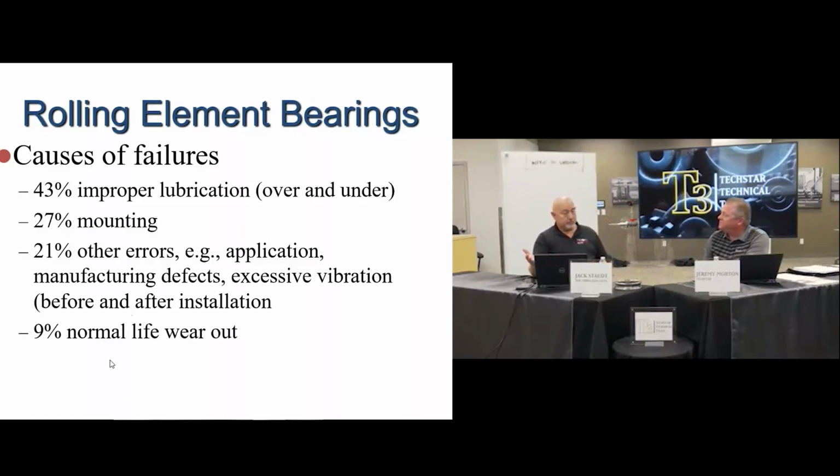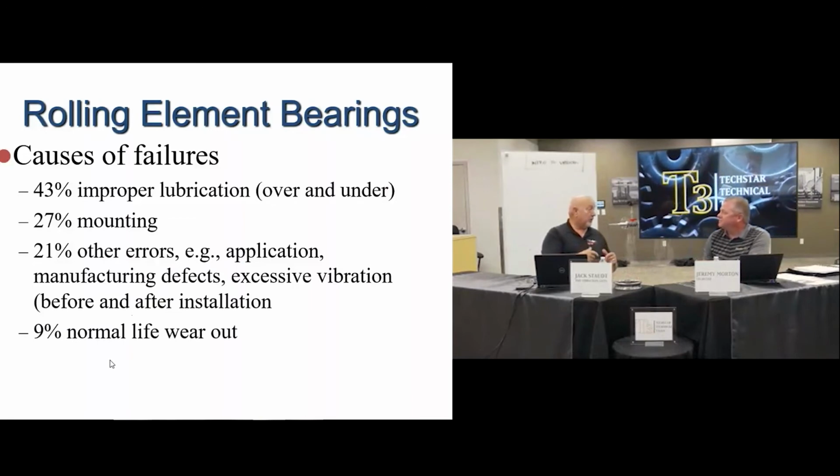Sure. Process has a lot to do with bearing defects. If you collect data and vibration shows it's running smooth, but somewhere in the process, when you're not collecting data, it goes through some type of anomaly or flow issue and jars it all the time, that could be killing your bearings too. So you wouldn't even think about it. Typically, yeah.